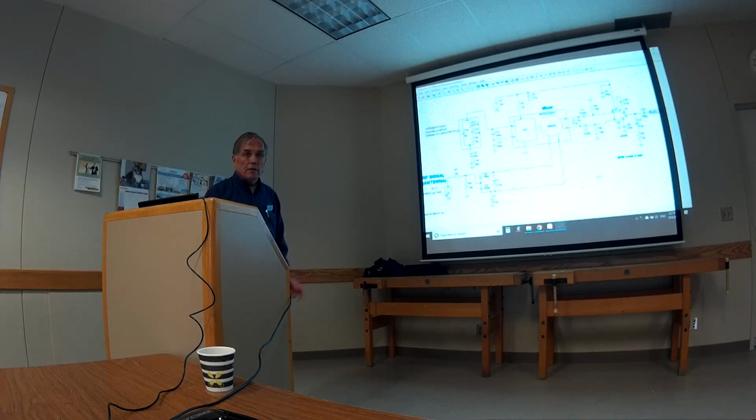So that's what I'm just specifying, a voltage down there. That's why you see it's so nice to simulate. We're just putting a voltage and making that into a sine wave at the frequency you want, and all these specifications just the way you want them. Then I just do a little bit of matching circuitry to make it match into the 1500 ohms that are specified for the input to an NE602. A little bit of low-pass filter. You see this 0.1 across here? That's going to take the high frequencies and shut them right out, and just let the low frequencies go on through the audio, which is what we want.